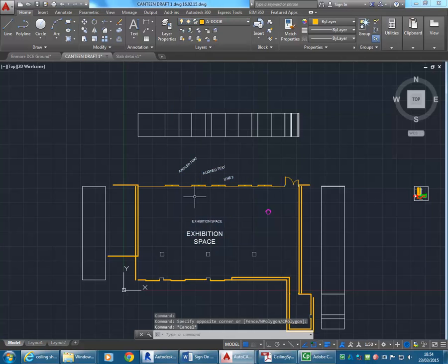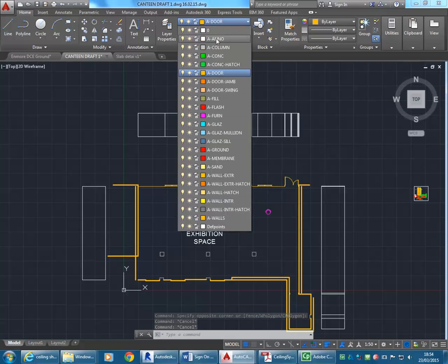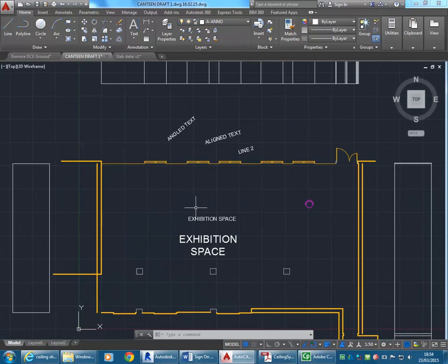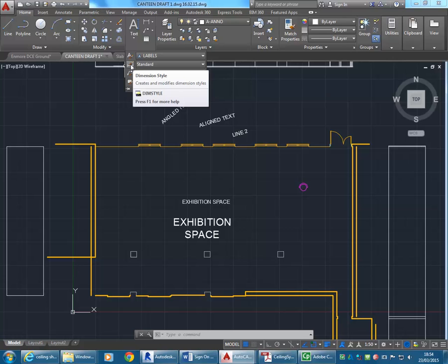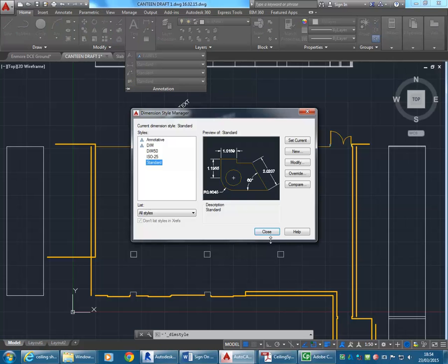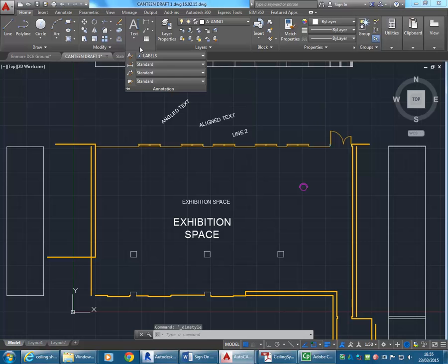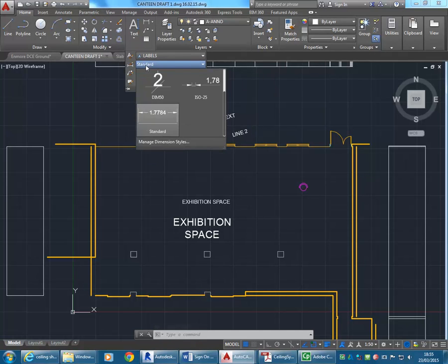Ano, that's what I've called it. And now I'm going to draw some dimensions, so I may as well switch to that layer, and then I'll set up my dimension style. So when you make your own dimension styles, same way as text, I better show you again. Under the annotation panel, you have the little button next to the list of your dimension styles. So looking at these, well, I've made one previously, dim 50, which is okay, but the other two are pretty awful.